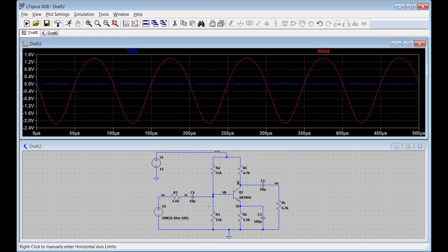The simulation should not be used in lieu of your understanding how something works. It's like, well, let's just simulate it. It's like, no. You should understand. You should be able to do a hand calculation. The simulation tool does all the grunt work for you, because we can run this over temperatures. We can change the supply voltage and see how this changes the gain of the circuit. And we can automate all of that. That is what the tool is for. It is not to think for you.